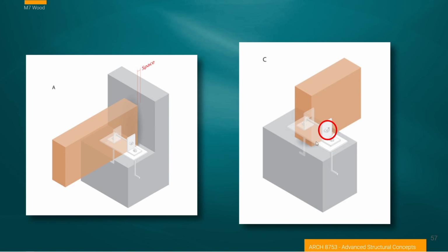So, anyway, one of the things you should start paying attention to when you look at the connector systems is the idea of slotting, of allowing for the natural changes according to moisture and natural expansion of the materials to not be destructive of their connection systems. And so that completes the introduction to mass timber and wood.